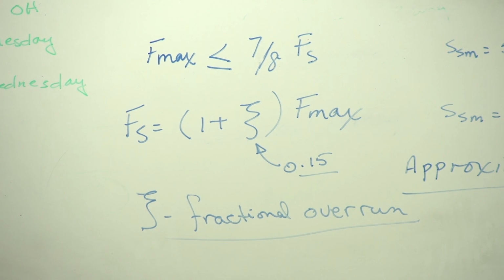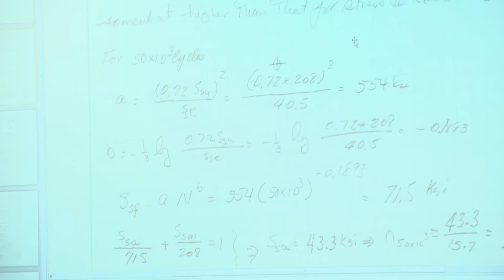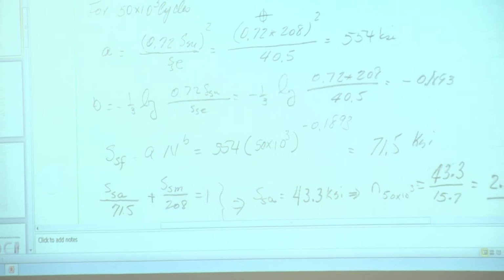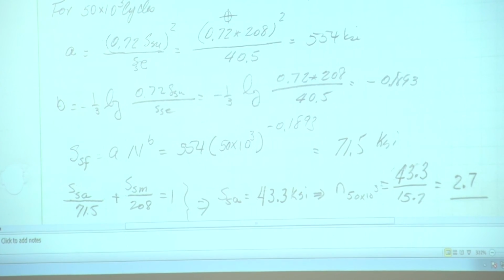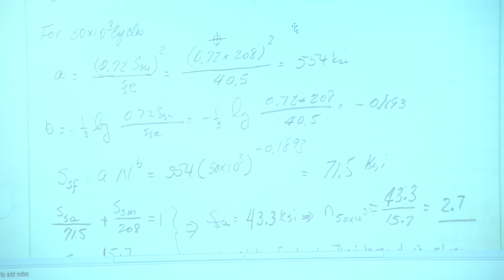So the factor of safety for torsional yielding for this maximum load should be somewhat higher because it doesn't yield at solid length. So there's no sense in calculating that unless you actually want the number. It's going to be a little bit over the factor of safety that we found.